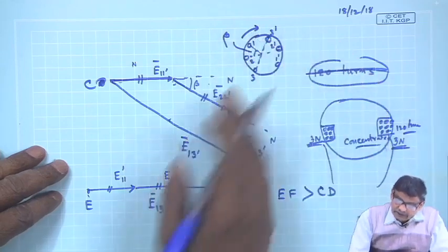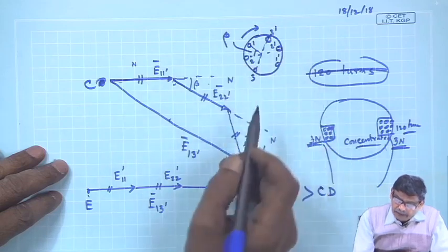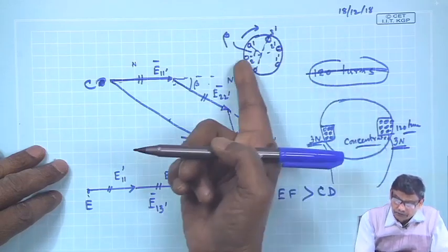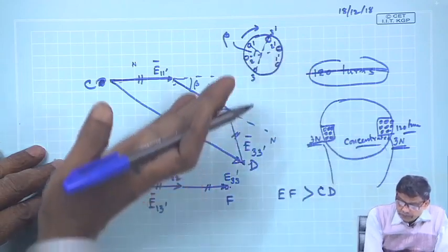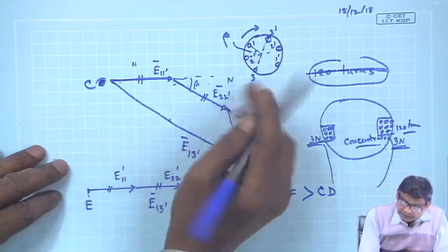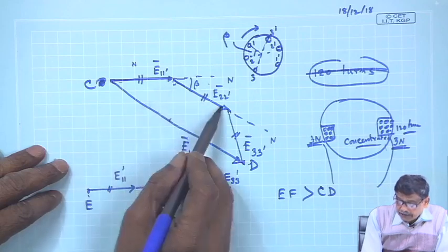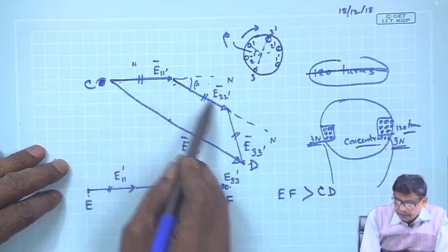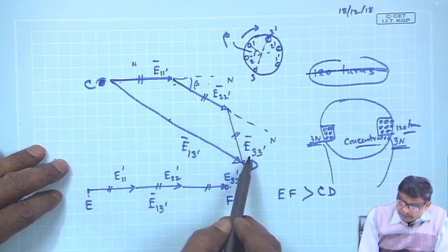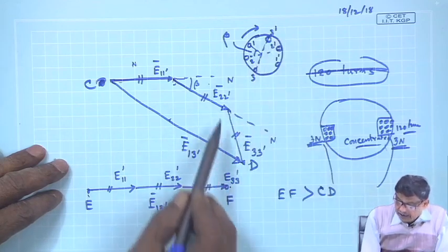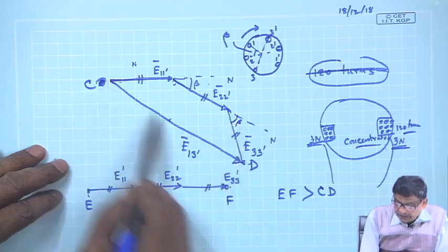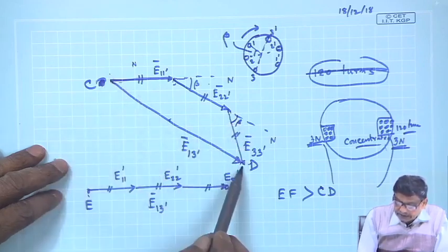and the direction of rotation I have assumed like this, and then whatever is happening to 1 dash now, the same thing is going to happen to 2 dash. Therefore, their phase voltages, the voltage across those coils, will lag 1 dash by beta, and then voltage 3 dash will lag by another beta angle, and so on, and the resultant RMS voltage will be this.